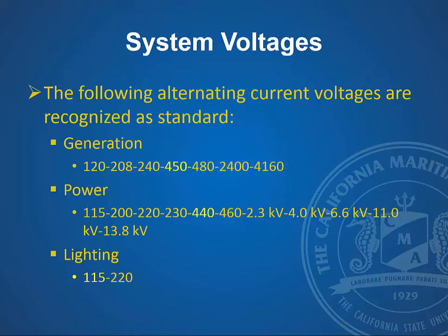These high voltages are on vessels that use electric propulsion, and you need that high voltage to keep the amperage going to the motors within reason. Also for lighting, it can be 115 or 220 volts, usually single phase.